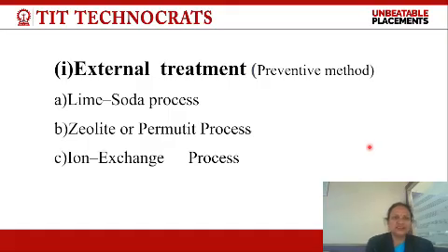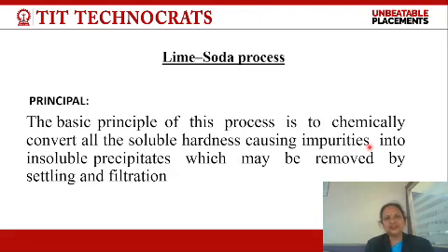This method contains three types: lime soda process, zeolite, and ion exchange. So students, first we will discuss the lime soda process. It is based on the principle that highly soluble hardness-causing salts or impurities are converted into insoluble precipitate by chemical reactions. This is the basic principle of the lime soda process.